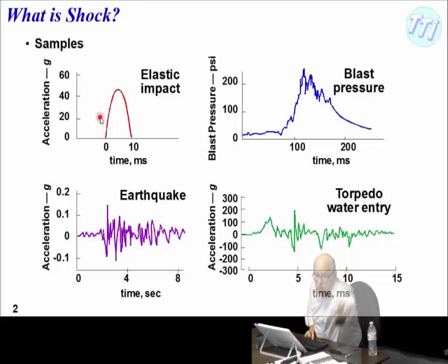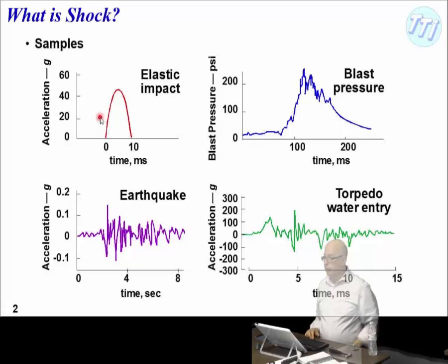If I take something like this, let go, that's very close to a half sine wave pulse. Have you ever done half sine wave pulsing on your shock machines? I have, but not on that one. You have not? No. If someone says go do a half sine shock on a shock machine, then the answer is no. You can do it on a drop test, but you cannot do it on a shaker table. And I'll show you why.